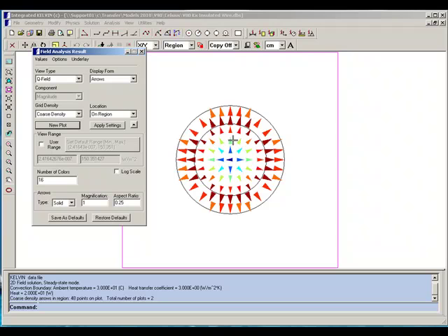The green arrows are a higher Q field, higher heat flux, and the maximum heat flux occurs right at the boundary, the interface between the copper and the rubber. Once you leave the copper and as you move through the rubber, the heat flux again decreases.